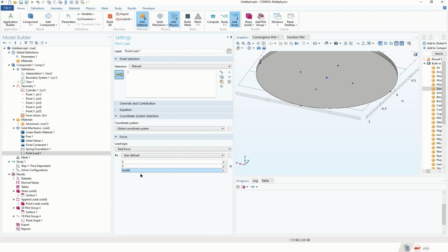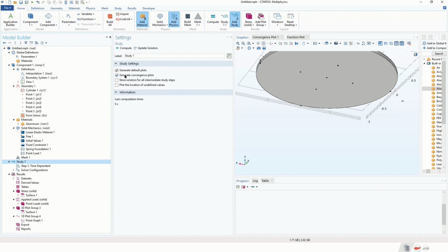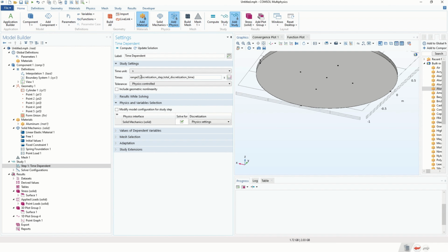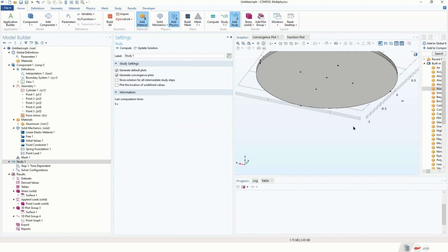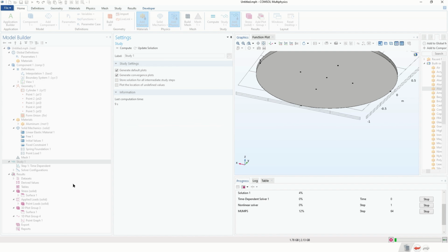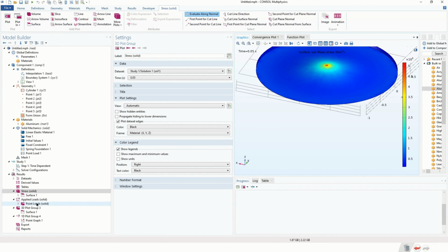Now, COMSOL knows that this function is defining a time. So whenever COMSOL is getting its results for, let's say, time 0.001, COMSOL is going to substitute that time here to compute our force. This is very important. We give some flexibility to our COMSOL simulations. And we click on compute. Okay, this will be a relatively quick simulation. I'm using a 16 GB RAM computer, i7 processor. The laptop is old, maybe 3 years old. Not too old. Okay, and this is what I'm getting.